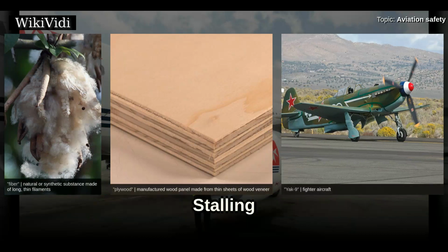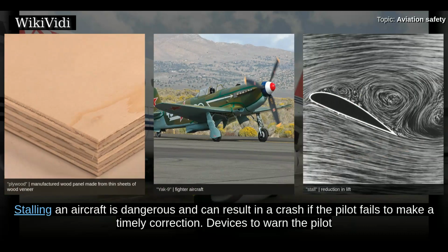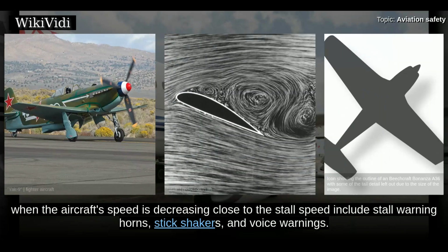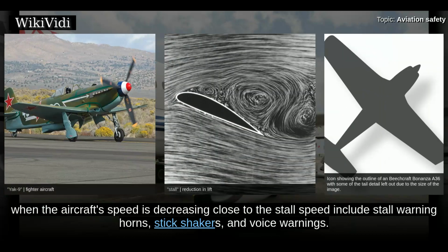Stalling. Stalling an aircraft is dangerous and can result in a crash if the pilot fails to make a timely correction. Devices to warn the pilot when the aircraft's speed is decreasing close to the stall speed include stall warning horns, stick shakers, and voice warnings.